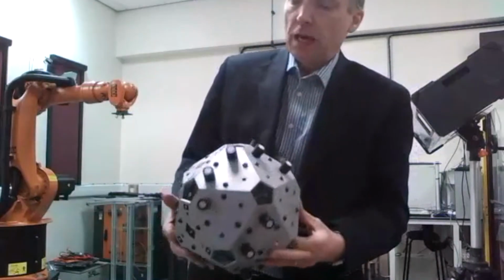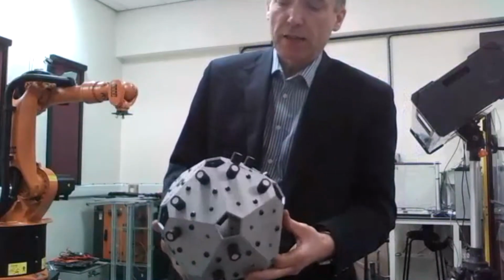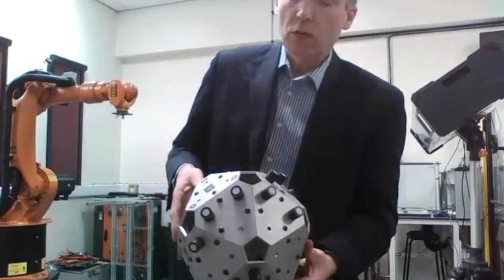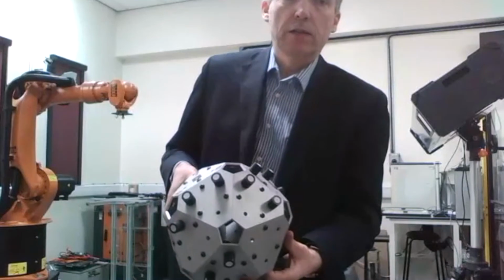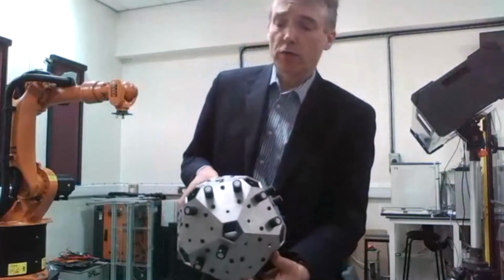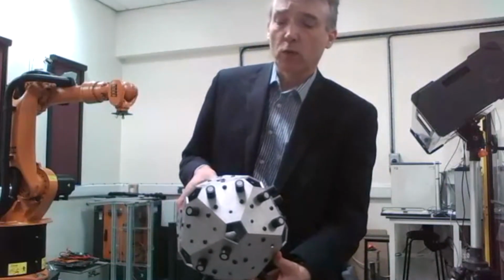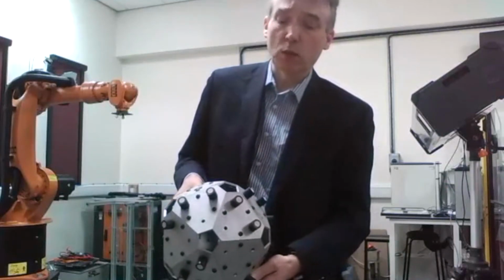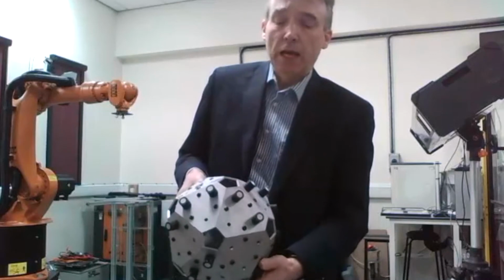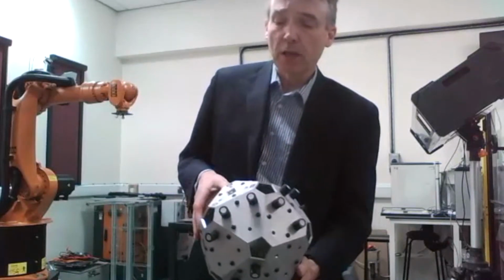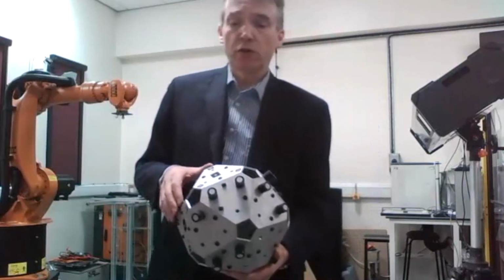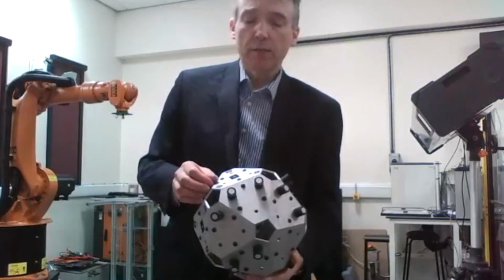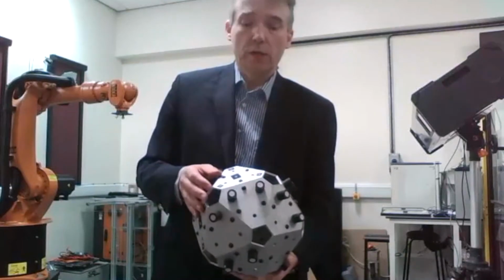And so the idea is that when you do the scan, for each of these little circles here, we can work out from the scanner the 3D shape of this part. We can work out what the scanner believes the center points, the XYZ coordinates, of those points are, and then we can compare that with a mechanical CMM, or coordinate measuring machine, that can actually touch all the way around these cylinders and work out what it believes the center coordinates to be.